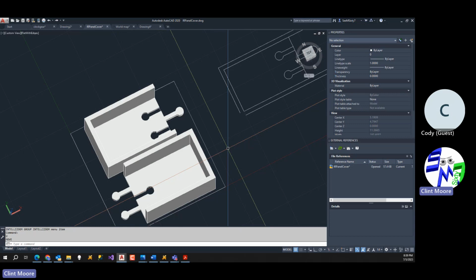And the problem is it's prompting you for a radius, and you're giving it a diameter. So you're actually making it 2 times as large as it needed to be. It's funny, because it popped it on there, started printing. I looked at it like, whoa, that thing is huge. What happened? And then it's like, oh, it's 2 times as big as it needs to be. It's a very common mistake. It's definitely something we all do.